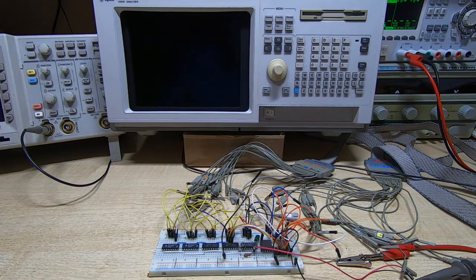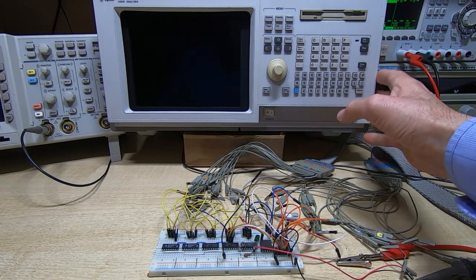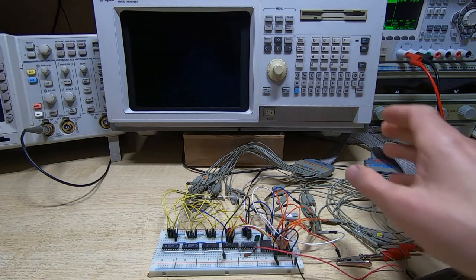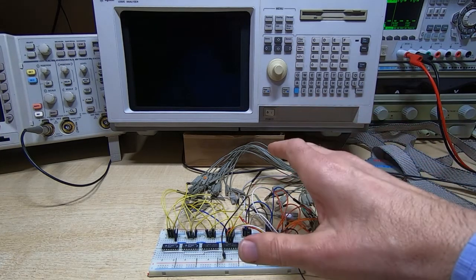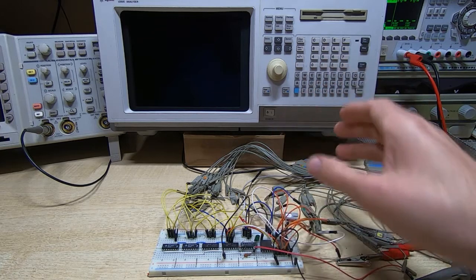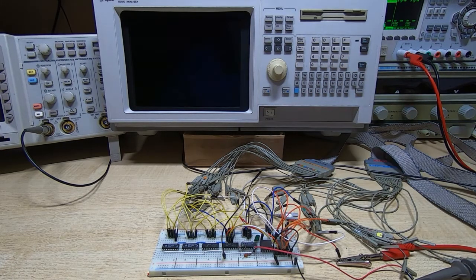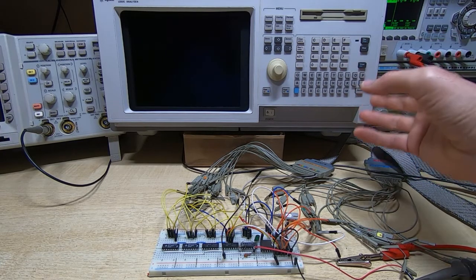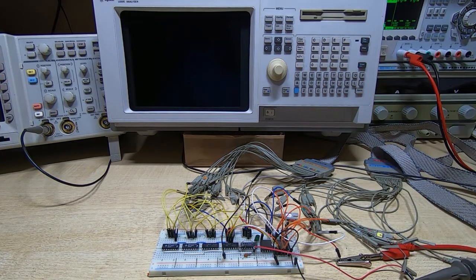particular machine. In the first videos in this series I went through how to set up the basics on the analyzer to do the basic configuration, and then how to connect the analyzer to a target board and set the input levels. And in this video we're going to be looking at how to set up a simple trigger sequence. With machines like this, the real power in them is in the trigger mechanism, the way that you can configure the trigger to capture data that you're interested in.